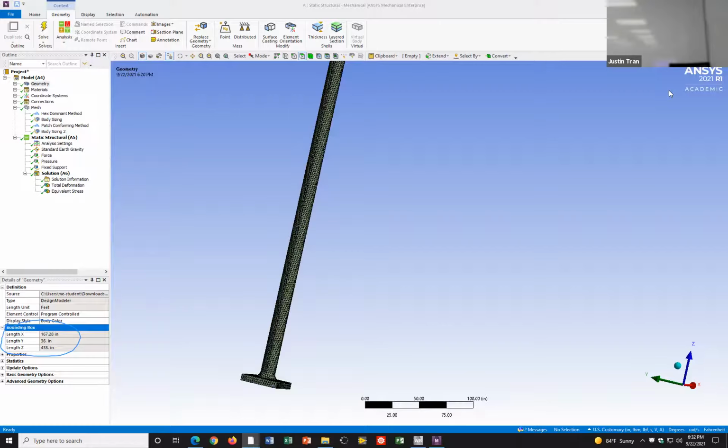Okay, so you can see here that typically you're going to get a max skewness of around 1. That's always just one random number. The average is the one that matters. Exactly. So your mesh is looking pretty good. Your average skewness is less than 0.2. You can look at the distribution. Most of your elements are in this one right here, which is good. So that's it. Okay, cool.